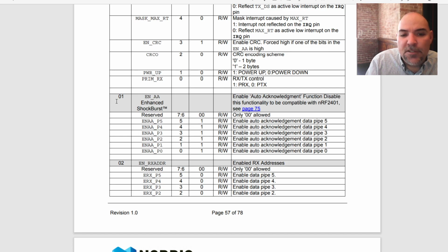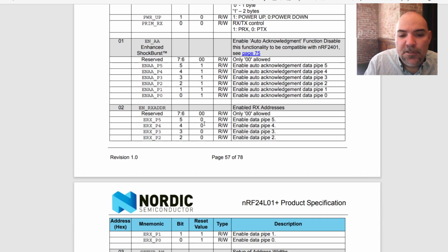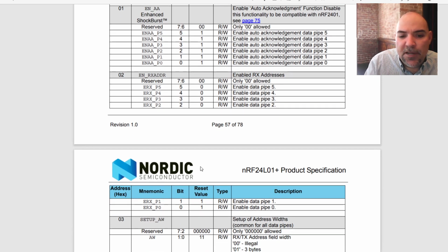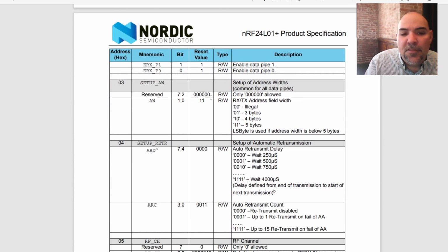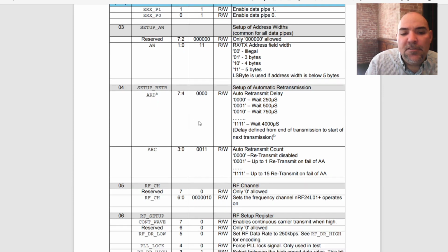And the next register, register 1, you should see 0011 1111. That would be 0x3f in hex, or 63 in decimal. And then for register 2, all of these read out as zeros except those. You should see a 3, 0x03, or just a 3. And then you should see a 3 in this register, a 3 in that register, and so forth.